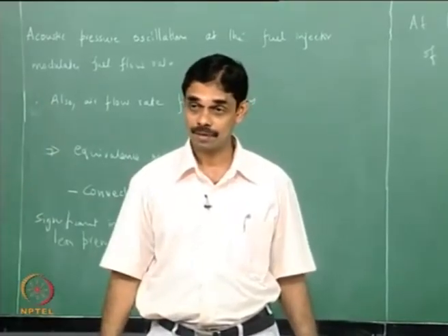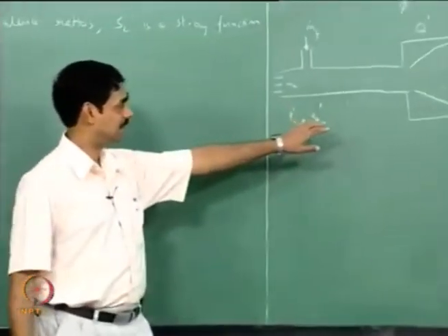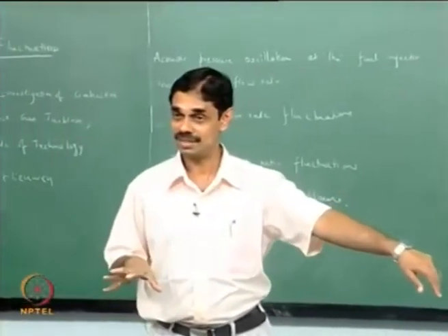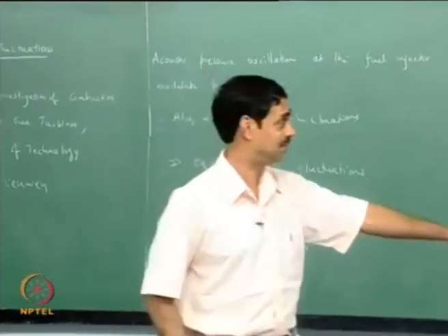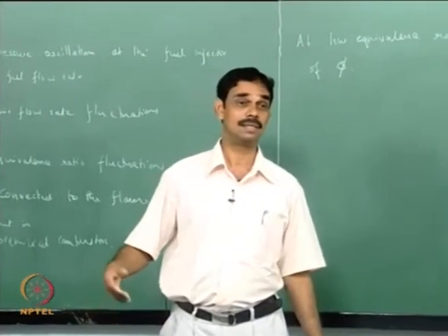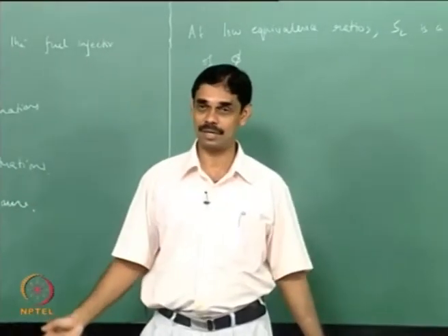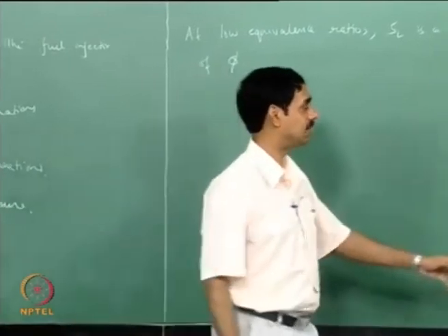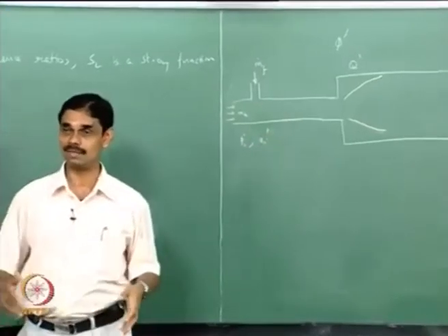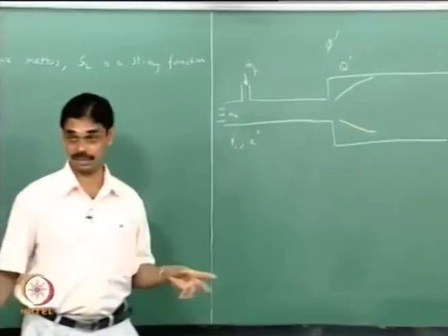In aircraft, you cannot have a separate tank. So these combustors are used in aircraft. It is not a premixed flame, by the way. It is a diffusion flame, and it burns liquid fuel. So we are not talking about that. We are talking about gas burners which burn natural gas or whatever other gas is available. Even if it's a liquid fuel, you can actually have injectors here to pre-vaporize the liquid. So LPP stands for lean premixed pre-vaporized also. Or you can have natural gas coming, one of these things.